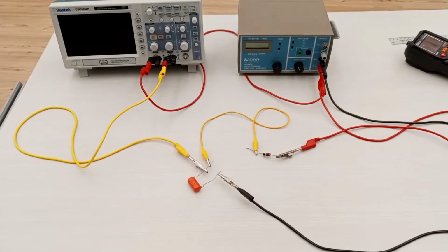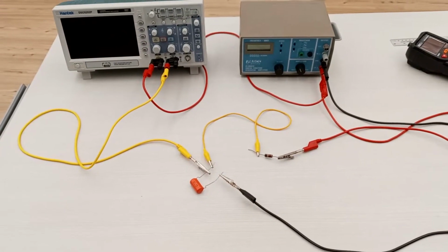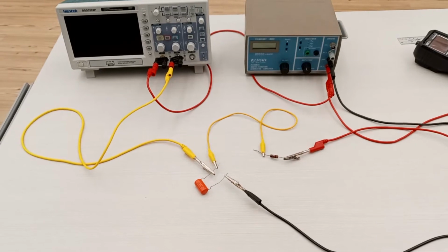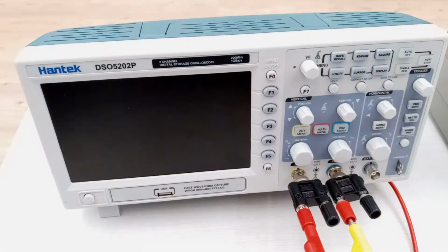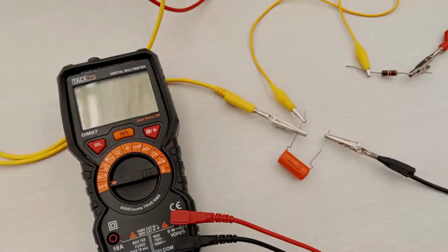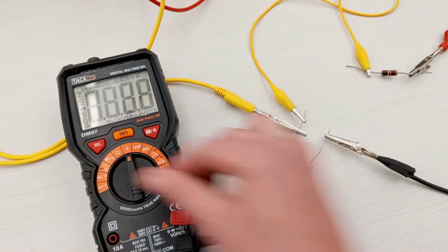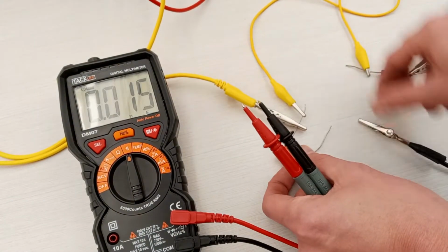In this experiment, you'll study the frequency domain behavior of a simple circuit containing a resistor and a capacitor. A signal generator allows us to produce time-varying voltages with different frequencies, amplitudes, and wave shapes. A digital oscilloscope allows us to view the waveform from the signal generator and the resulting voltage from different parts of our circuit. First, we use a meter to measure the component values of our resistor and capacitor.